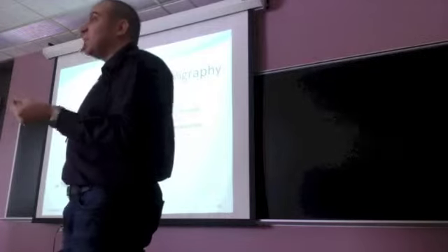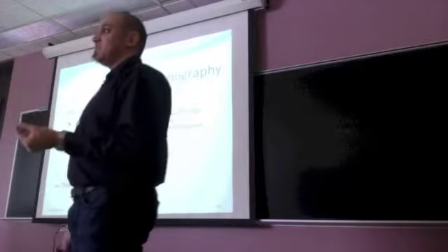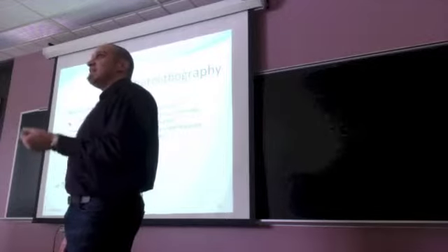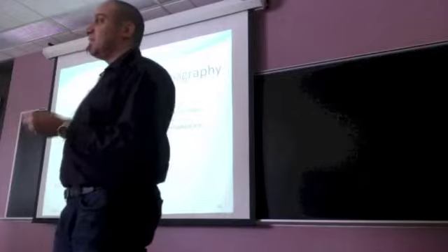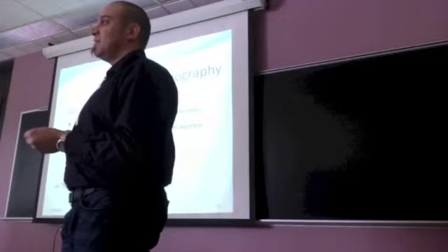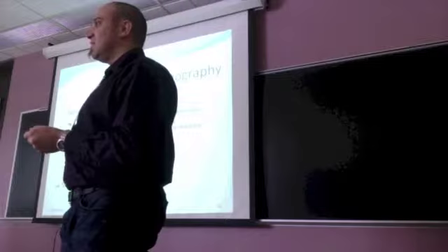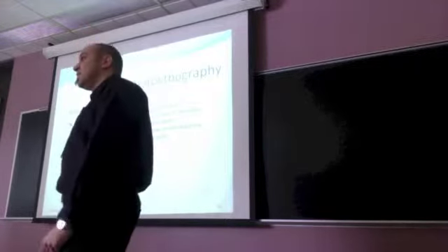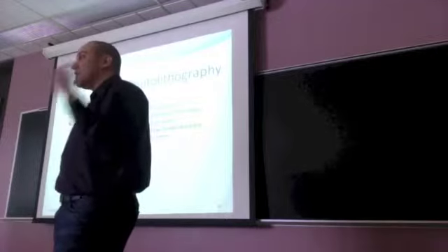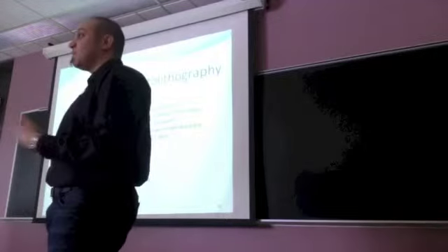It's awful. And normally, I think that the minimum size should be 1 by 1 centimeters. And for sure, with 3 by 3 it will be very difficult to get a uniform layer. And even with the tools we have for photolithography and the vacuum to hold the sample during the process, it will be very hard.